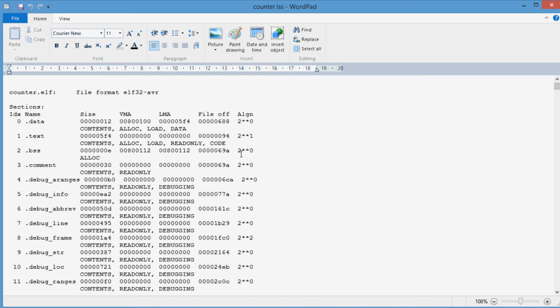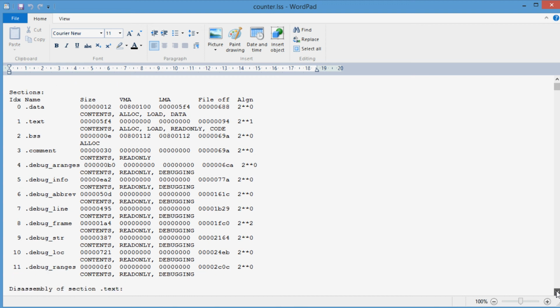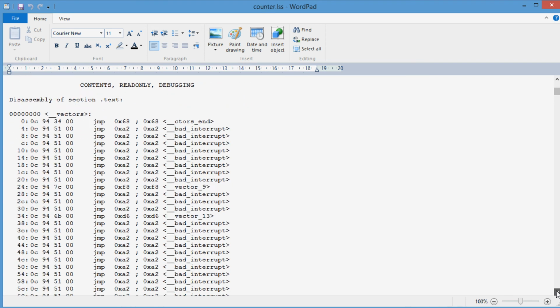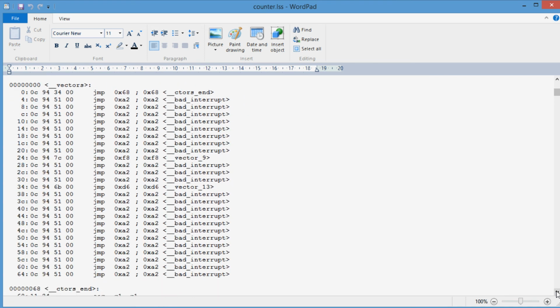When you're using Atmel Studio, it's set up so that it does produce this. It's called a listing file, where it actually shows you the native instructions that the microcontroller executes, that the compiler puts together. So in this column here is the address in flash, starting at 0. And these are where the instructions are stored. And the first thing that's in the memory is this vector table.